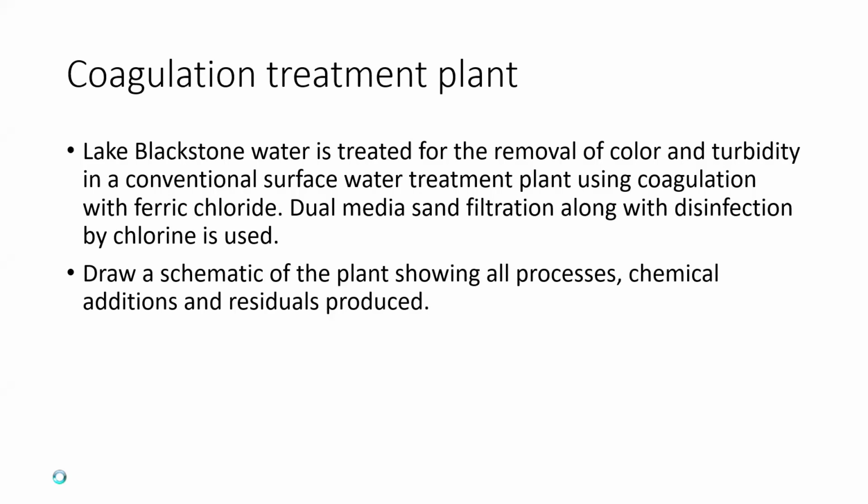So we've got Lake Blackstone water. It's being treated for the removal of color and turbidity in a conventional surface water treatment plant. It uses coagulation with ferric chloride. It also uses dual media sand filtration with disinfection by chlorine.